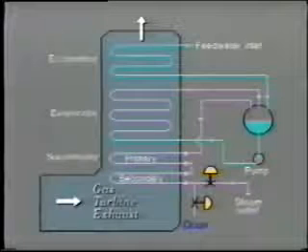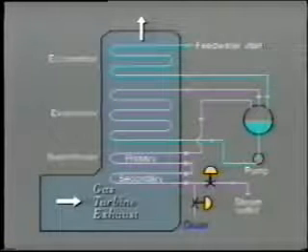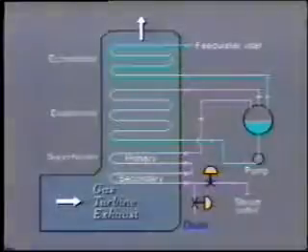In order to assist in draining condensed steam from the superheater, a horizontal arrangement is sometimes employed like this. In this case, the lower header drains can be opened during startup to drain off any accumulation of condensate.